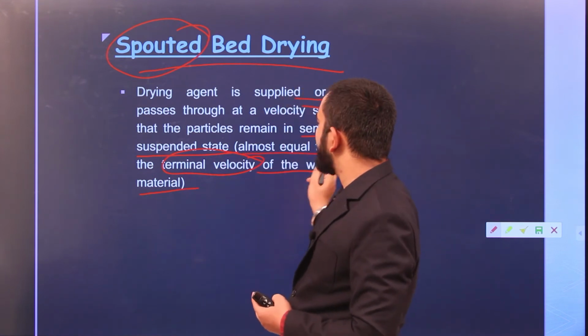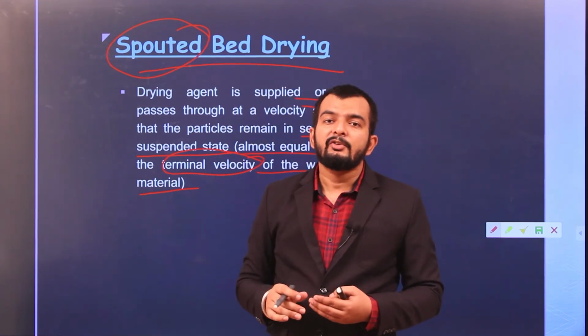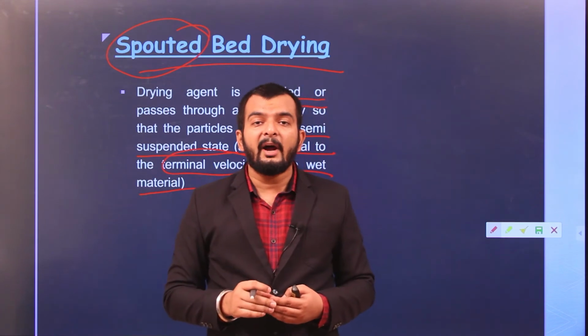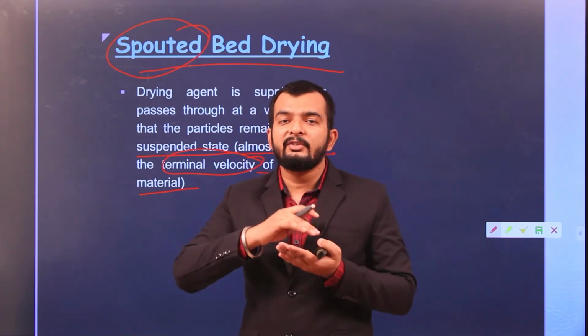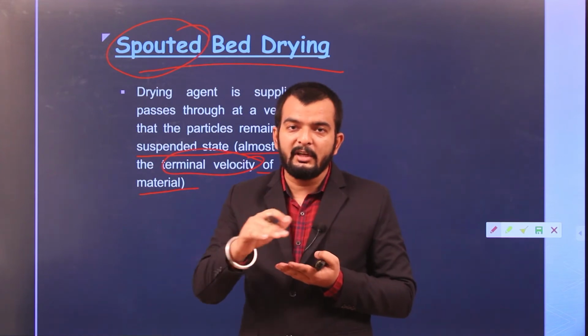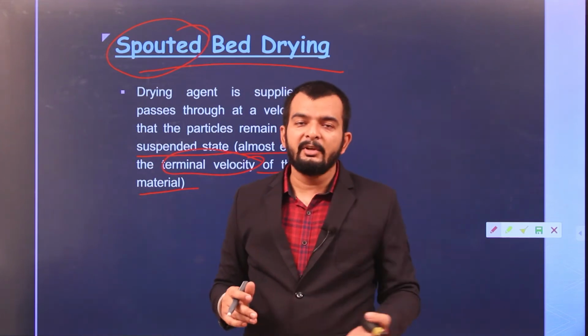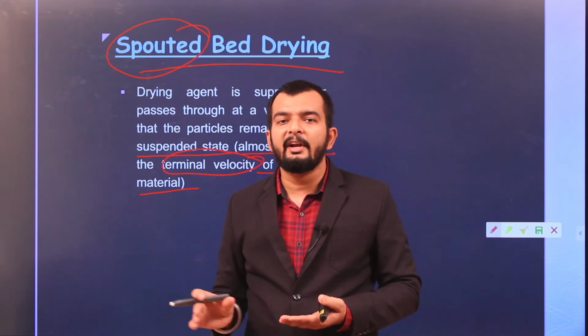It is almost equal, maybe slightly less, so that your grains or food particles which are to be dried will remain in semi-suspension. They will not start to float in the bed, and they will not simply lie down at the bottom.